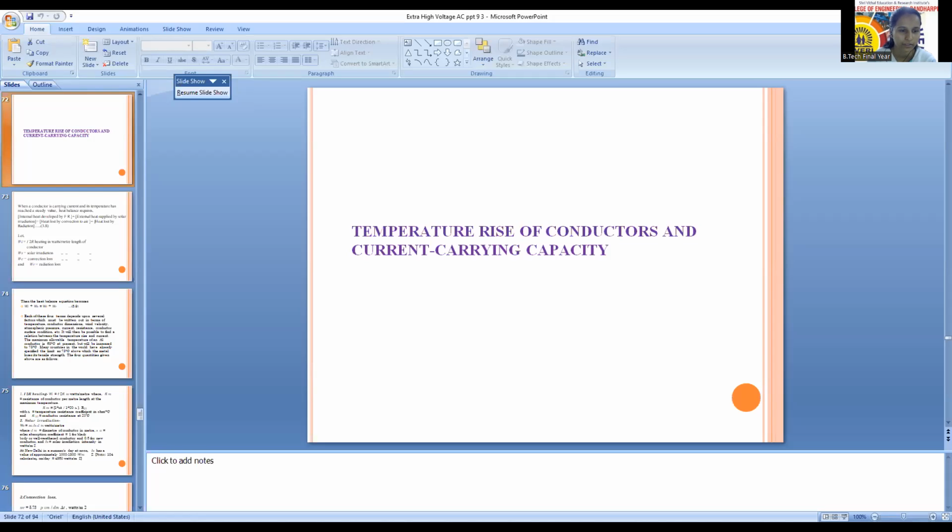Ws is the solar radiation, the solar irradiation supplied in watts per meter length of conductor. Wc is the convection loss, also given in watts per meter length of conductor. And Wr is the radiation loss, the last term of equation 3.8.